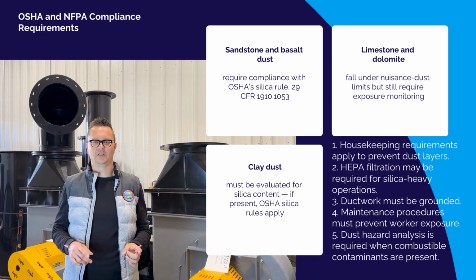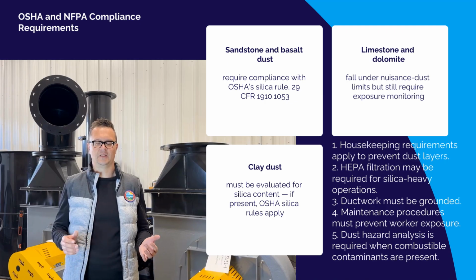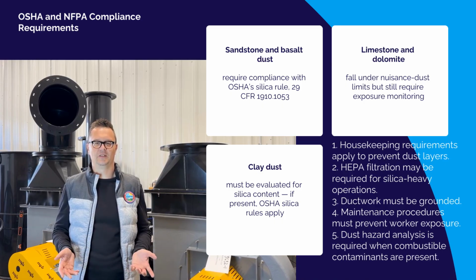First, housekeeping requirements apply to prevent dust layers. Second, HEPA filtration may be required for silica-heavy operations. Third, ductwork must be grounded. Fourth, maintenance procedures must prevent worker exposure. Fifth, dust hazard analysis is required when combustible contaminants are present.